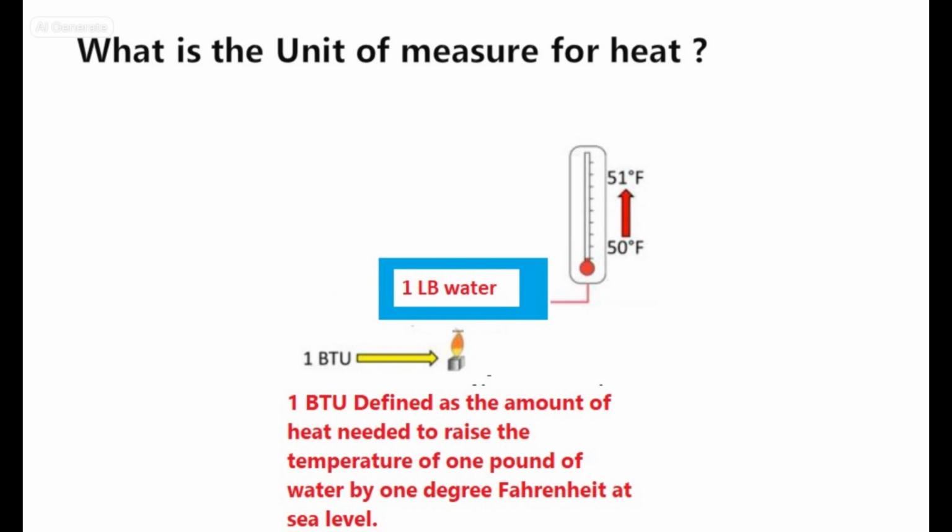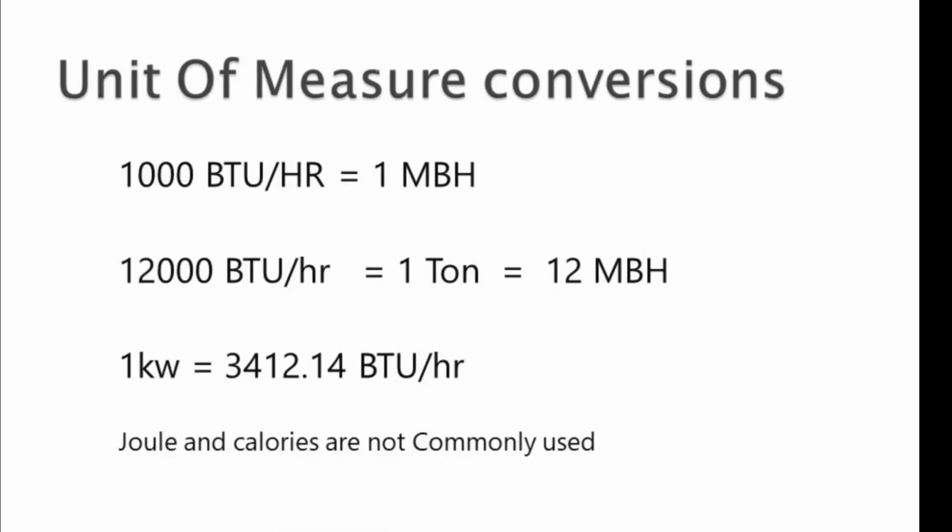Heating or cooling units are rated by how many British thermal units they can handle within an hour. In other words, the unit can produce refrigerant that can absorb heat within an hour. In general, we say a 12,000 BTU unit. This means the compressor can produce refrigerant that can absorb 12,000 British thermal units within 1 hour. I hope you understand what British thermal units per hour means.